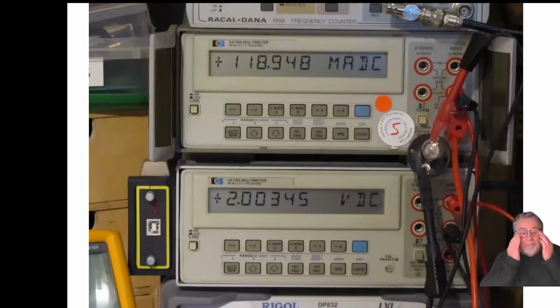There is a humble bulb. Over to the right-hand side of that picture, you will see a 12-volt, 5-watt side light bulb of a 1978 MGB. It's in a batten holder that's from 1968, I think. And I think the multimeters are about the same age. What we have there is a power supply at the bottom of the page, driving the bulb through the milliammeter. And the voltmeter is directly across the bulb. So I've got a bulb and I'm putting a varying voltage in it and I'm watching how much current flows.